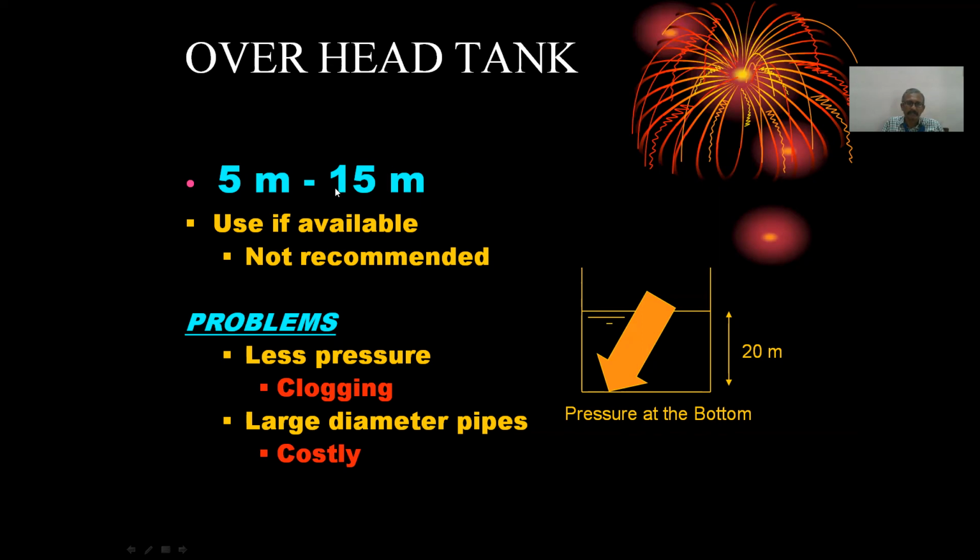Sometimes in some books you will also find 5 meters to 17, 20 like that. The higher boundary depends on what kind of filters you use. And normally if you have around 10 meters of pressure head, one will be able to make the drip irrigation system function very well. 5 meters and all will be very, very low. And for pressurizing the irrigation water at the source, one can provide an overhead tank and do the job.